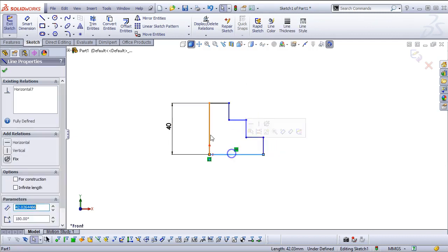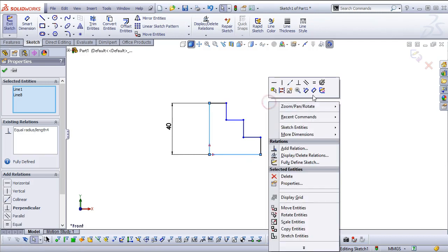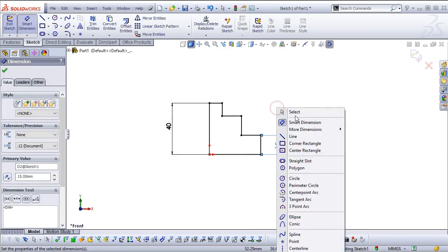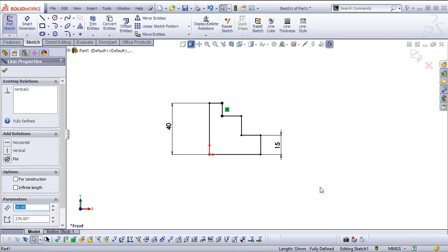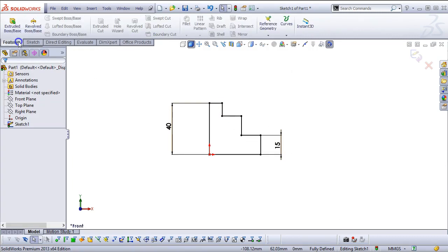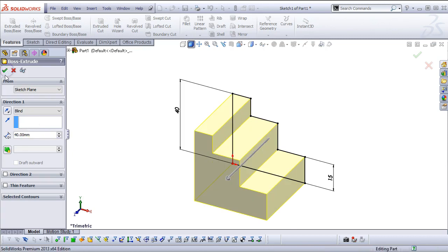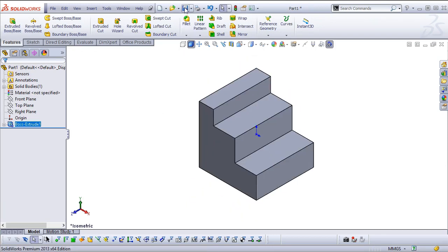And then 40 millimeters on the width, so same thing, select, control, select. We'll go to equal and put in a few dimensions, and that will cause it to go fully defined. So the remaining should be 10 millimeters high. I didn't really need a dimension there, so let's escape a couple times. 10 millimeters high, 10 millimeters long, and now we're going to set it for a depth of 40 millimeters. Okay, and then we'll go to Control 7 and perform the save.